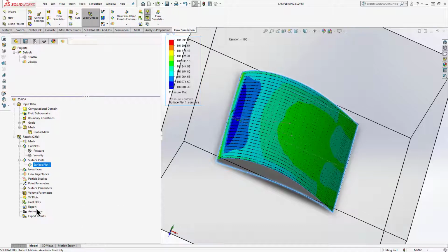in the wind tunnel. So our takeaway from this is, in our foil sim, we could create a wing and estimate what it would do in terms of lift and drag. We could design a wing or take a designed wing and fly that wing in our wind tunnel and see physical things like lift and drag alter based upon angle of attack and speed. And we could see a stall developing as we got to those extreme angles of attack by the thread starting to pick up off of the wing.